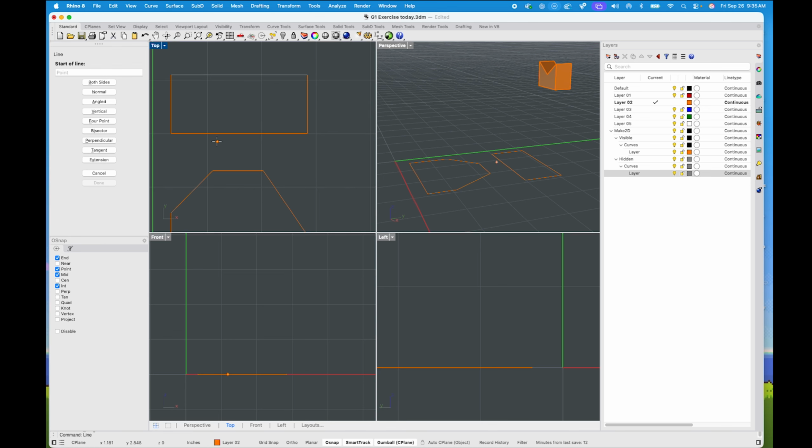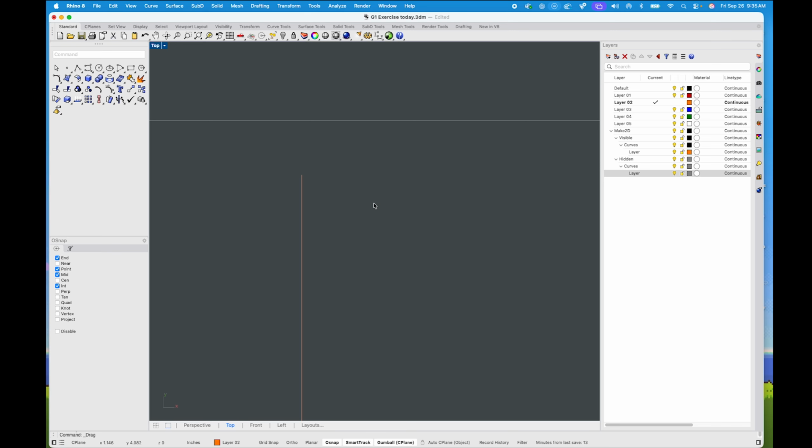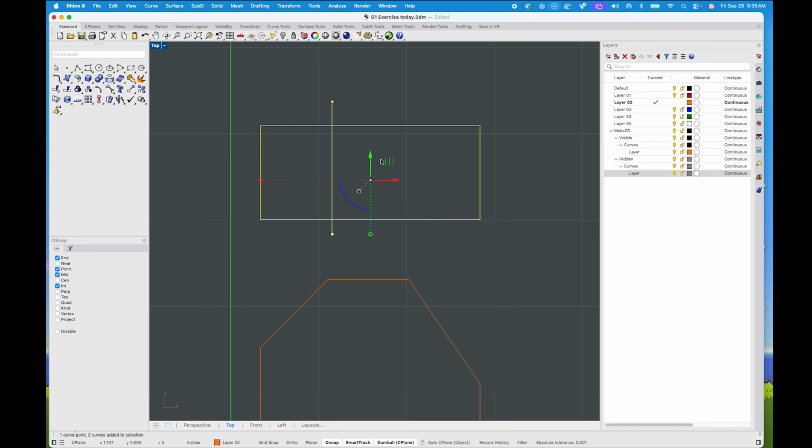You're good. Another thing I can do is trim something, right? So you'll see that I just drew a line like that. And, well, man, that's not good. And I definitely don't want to just sit here all day trying to line up things and only to realize, oh man, they're not even really lined up. So don't try to do everything manually. In fact, we can trim something. So I can take everything, trim, enter, and then basically click on the thing that I want to get rid of. Not too shabby, right?